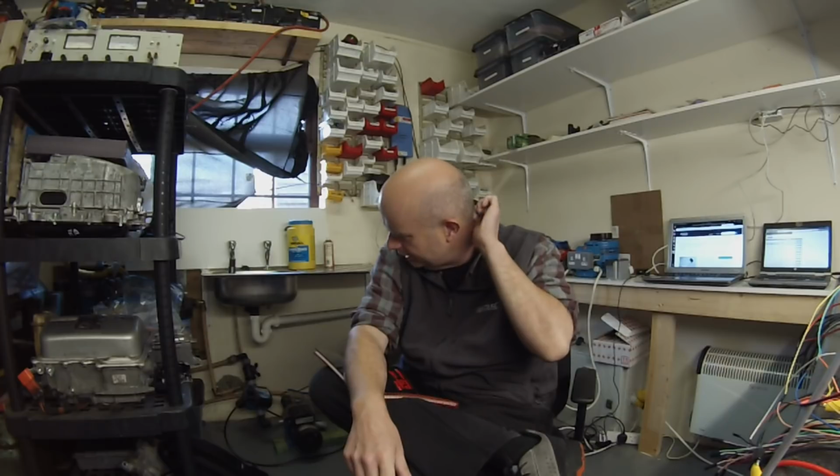Pre-charge on basically means that you dump off the main contactor, but you leave the pre-charge relay on. Now there's a third option called all on, which leaves on the main contactor and the pre-charge, but basically shuts the power stage down.